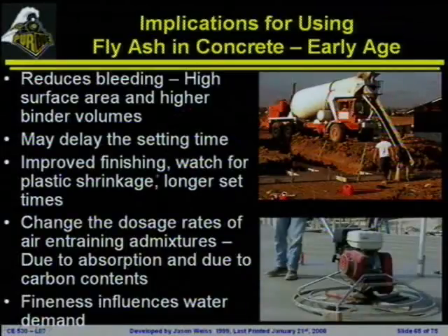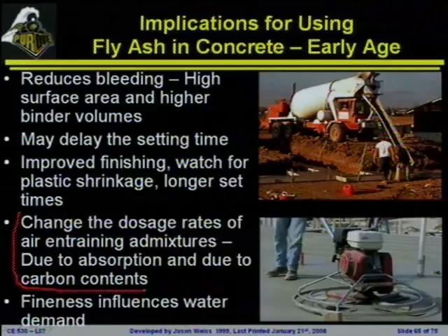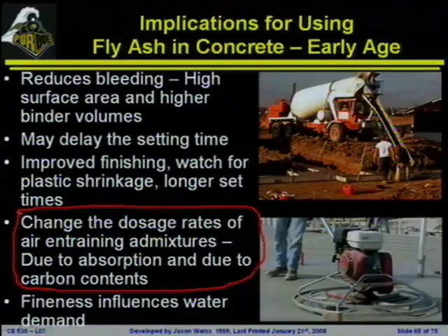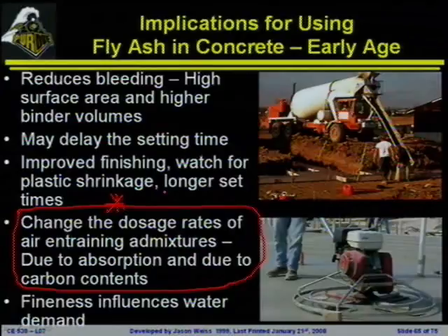You will also notice one of the biggest things, and I will point this out here. We'll talk about this briefly in a second. One of the biggest problems with using fly ash, or quality control on fly ash, is looking at the dosage rate for your air entraining admixture. One of the big things that people get very worried about with fly ash is how much carbon you have in that fly ash, because carbon, some of you will know who have air filters at home, or you've got a roommate who's running that air filter constantly.